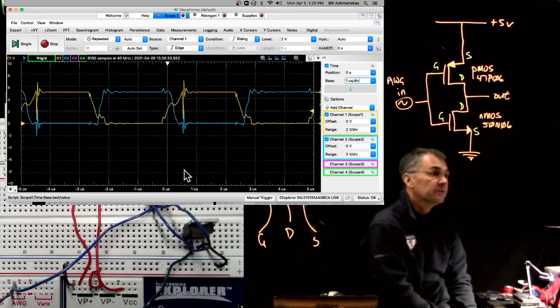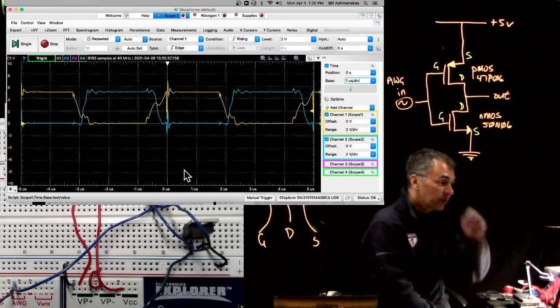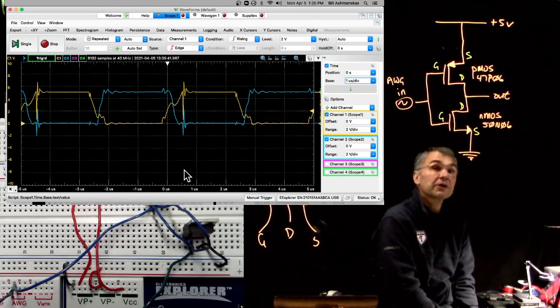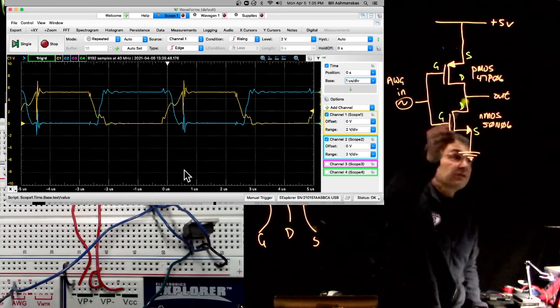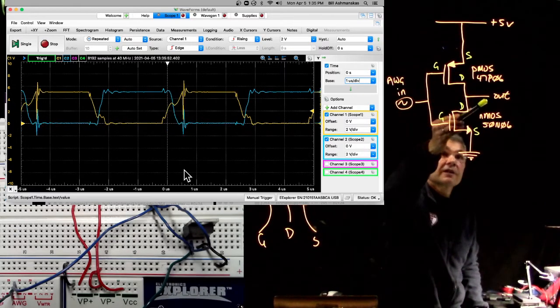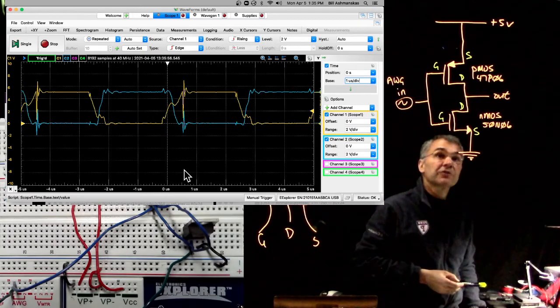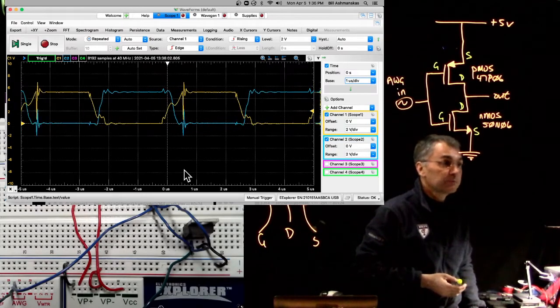But I think it does as well both going from low to high and going from high to low as the NMOS did when its output was going from high to low. Because in this case, the output is affirmatively pulled either down to ground or up to +5 by one of the two transistors, instead of having to be weakly pulled through the pull-up resistor.